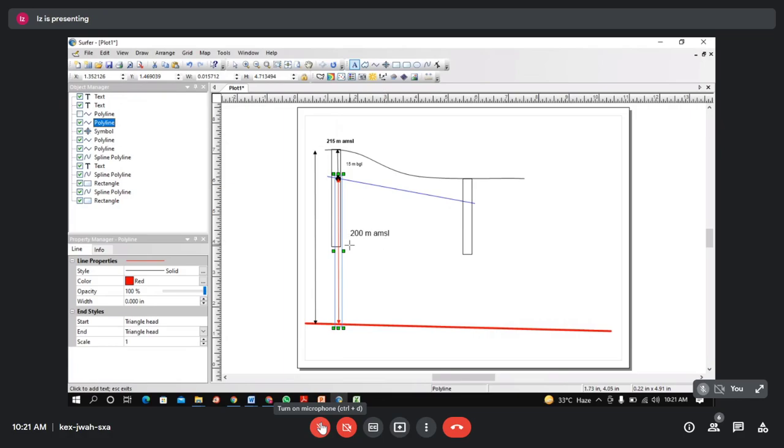Now all these values, once you convert to water table contour map, and this also can be done if you are working on a raster file, right? We can do one raster of topography and one raster of the depth to water, and you just do the subtraction, you will get this surface, which is the water table contour map. We'll do it now.